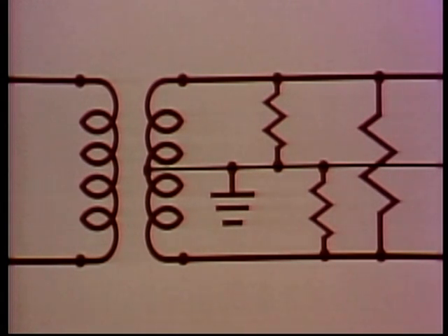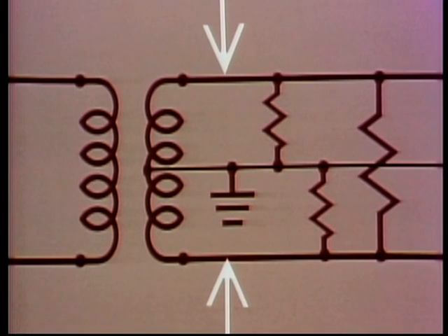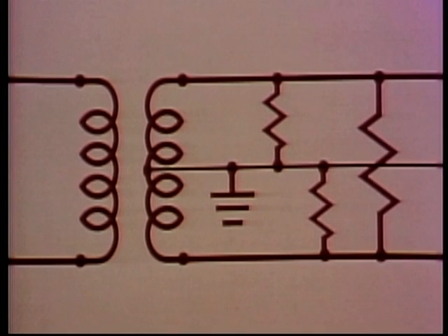There's something else we can do with these three wires, though. We can use the two outside lines to get 220 volts. Thus, the three wires give us the 110, 220-volt system that is most useful for home and plant applications. Before we leave this diagram, I want to mention one more thing about the neutral line.